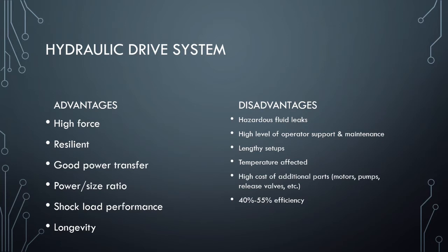There's also typically lengthy setups involved when you're bringing in one of these systems. There's a lot to them, so it can take a little bit longer to get them up and going. And because they are using hydraulic fluid, they are subject to temperature fluctuations. So depending on the thermal coefficient on that fluid, at certain temperatures, the fluid can expand or it can contract at colder temperatures, and this affects how the drive system functions. So you do have to bear in mind what temperatures these are going to be operated in.